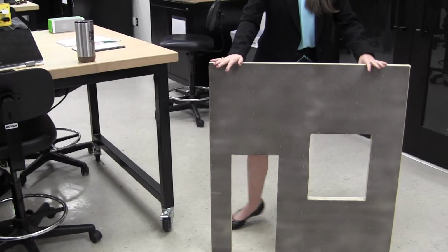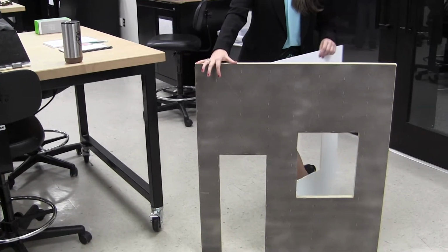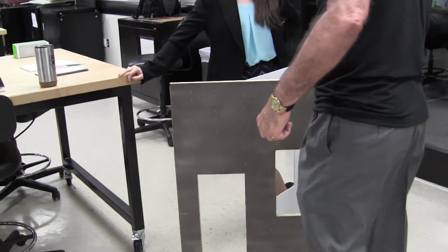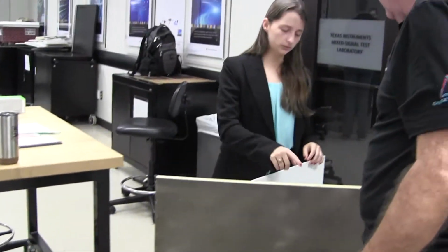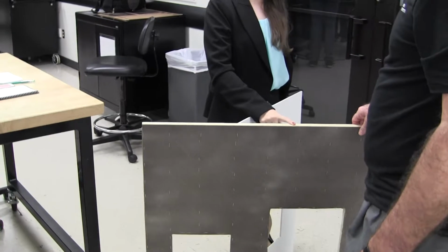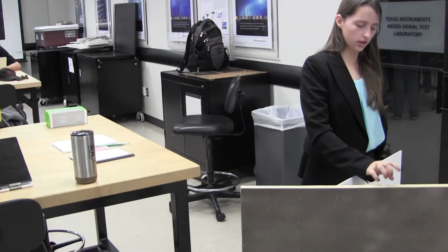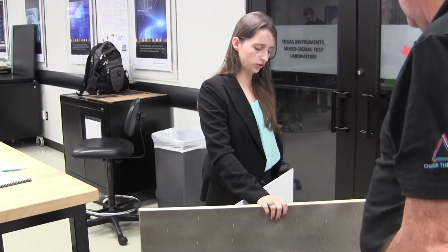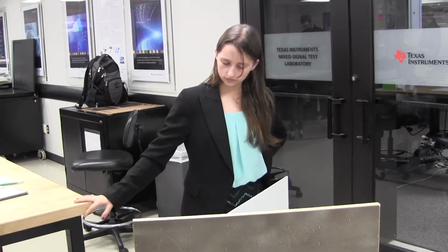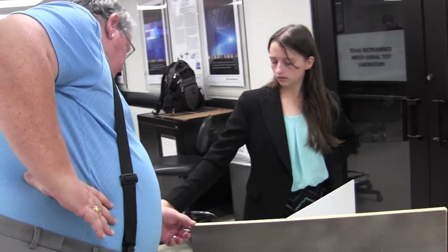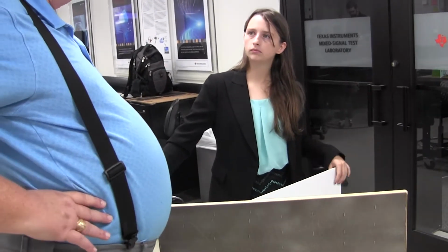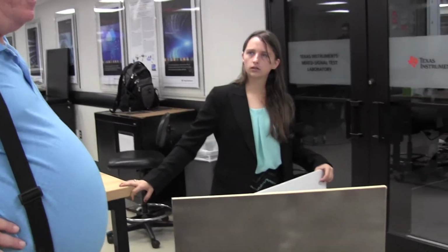Okay. And that's what I show you. But wood-wise, you think constructing it, it will be okay? Yeah, I mean, this held together really well. Once we put on the inside and outside wall, I would glue it and nail it if I were you. Just get some good wood glue to do that with, and it'll be fine. But if you're going to nail, this wood is thin enough that you're going to want to pre-drill all those holes. So you'll need a drill motor and a small bit.